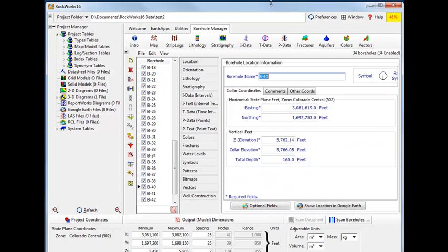The spacing of these nodes in the grid models will affect the accuracy of the models. The spacing setting is defined here in the Output Dimensions area. If you've used the Scan Boreholes button to set these dimensions, be very sure to look at the spacing setting that was assigned. If your holes are 25 feet apart and the node spacing here is set to, say, 100, then these grid models won't represent your data very well. Be sure to look at the node spacing. The range of the axis coordinates divided by the spacing gives the number of nodes.